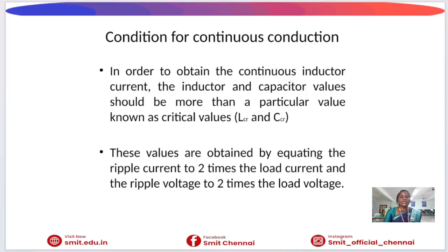In continuous conduction mode, the inductor current never falls to zero. To maintain this operating mode, the inductance and capacitance must be greater than certain critical values. These values are known as critical inductance and critical capacitance. Continuous conduction operation provides better efficiency and smoother current flow.